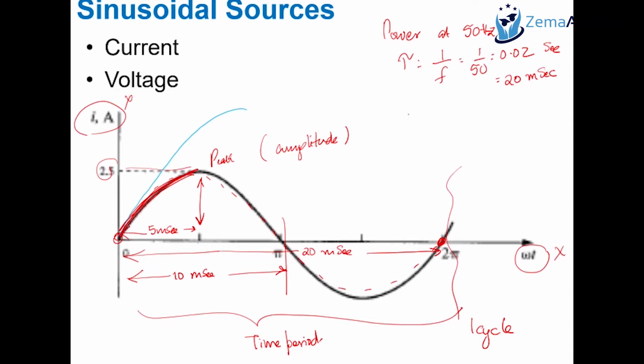So usually circuit breakers operate in the first 2 to 3 cycles. So if each cycle is about 20 milliseconds, 2 to 3 cycles would be 40 to 60 milliseconds. And if you compare that to a time scale of a second, you know how short that window is, which means how quickly these circuit protective devices should act as well.